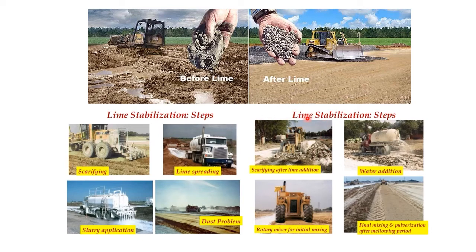Spread the soil to the required grade and compact it using rollers. Compaction should achieve the required maximum dry density. The compacted lime soil layer is allowed moist curing for 1 week. Field tests are conducted to check the water content and maximum dry density of the compacted soil.